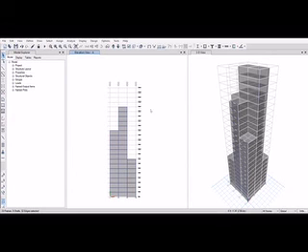Check for the wind pressure coefficient under this category. The coefficients are 0.8, minus 0.25, minus 0.8 and minus 0.8 for sides A, B, C and D respectively, as per the building plan in the IS code. Now in the software, select all the shells. All the shells are already selected.